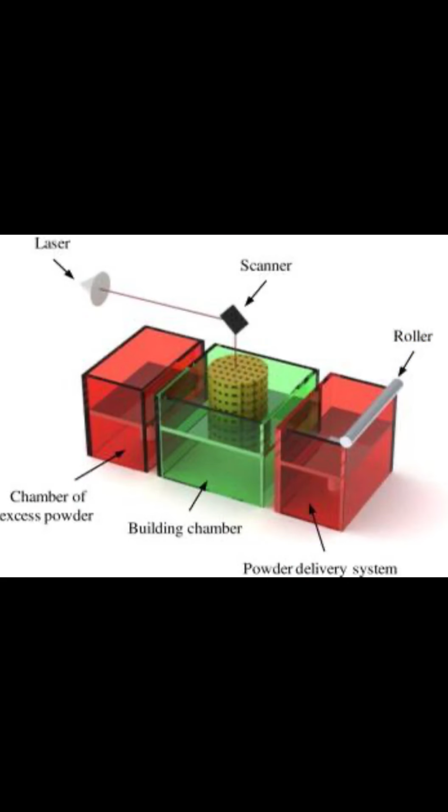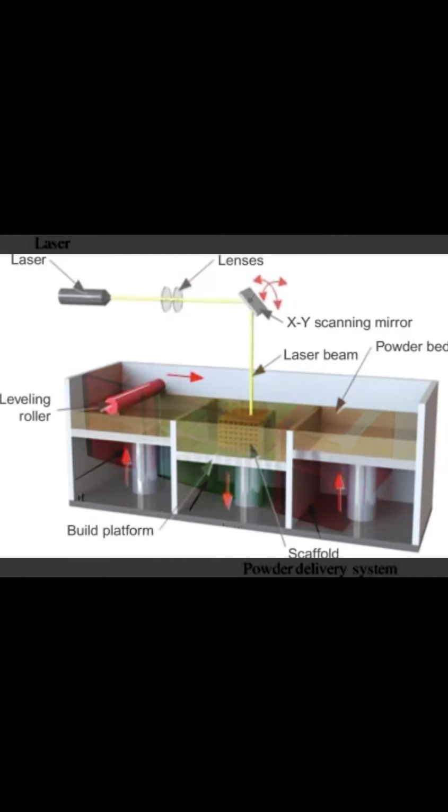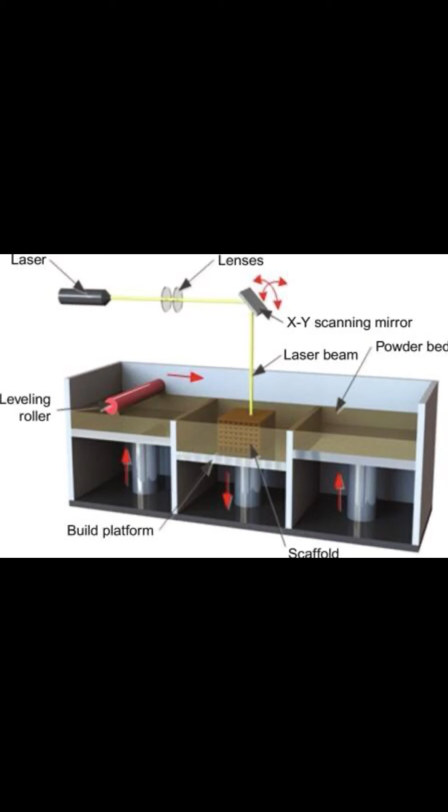Powder bed fusion is an additive manufacturing process and works on the same basic principle in that parts are formed through adding material rather than subtracting it through conventional forming operations such as milling. The PBF process begins with the creation of a 3D CAD model, which is numerically sliced into several discrete layers.